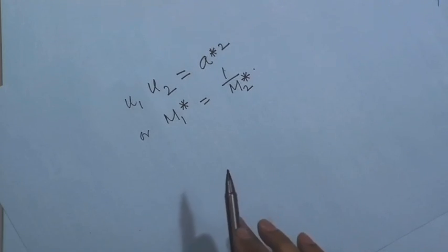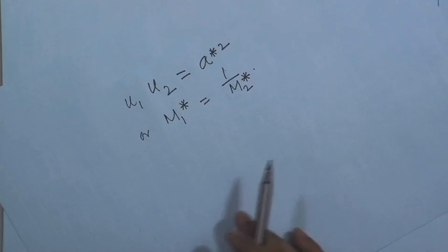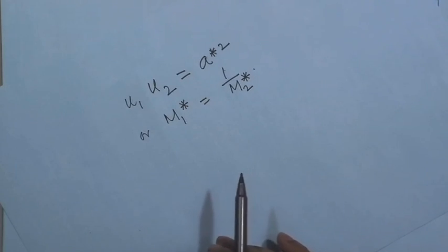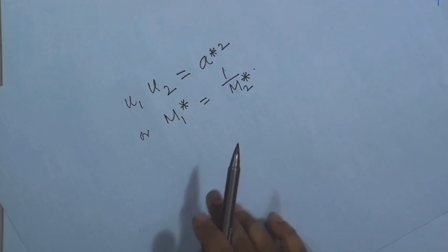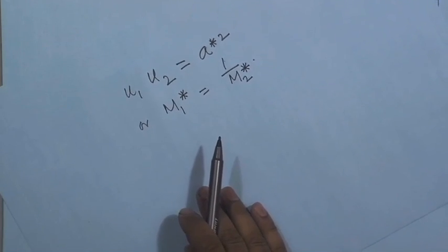However, there is nothing in this relation that excludes one of these possibilities. However, as we have mentioned, on physical grounds, if there is some sort of non-equilibrium region between station 1 and station 2, where viscous effects or heat transfer are present, then through these dissipative processes, acceleration of the flow is physically not possible, and the jump from subsonic to supersonic most probably will not occur in a real flow.